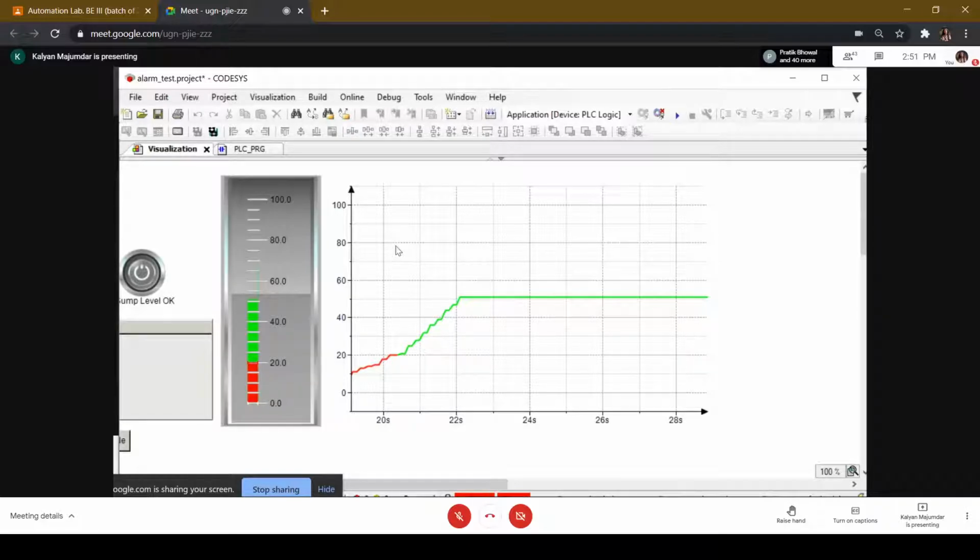So the basic difference between trace and trend is the amount of time for which you can store the data. Trace is just the current time plus a little amount of history, 10 seconds, 1 minute or whatever. And trend is a very long duration history, could be even in the range of months, provided the necessary storage capacity is present in your server.